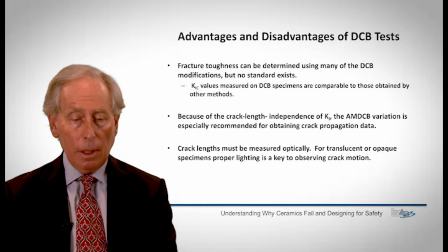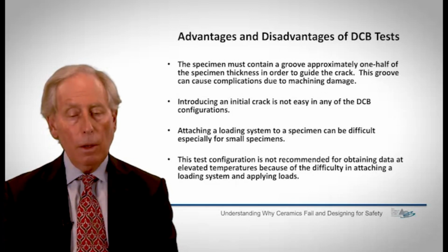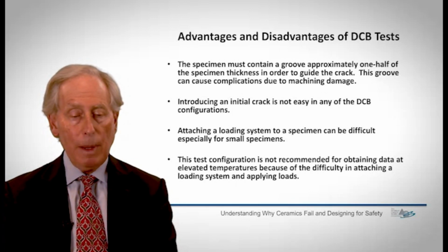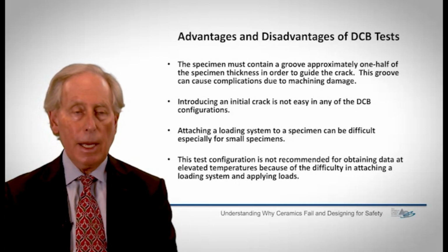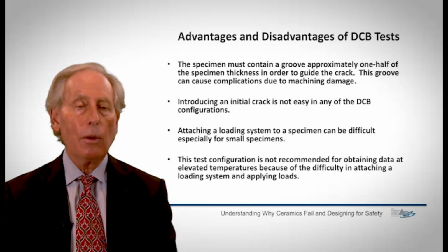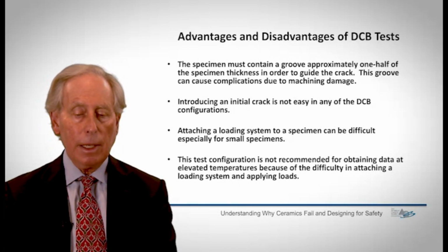In addition, I mentioned this groove. The groove is about halfway through the specimen in thickness to guide the crack, and the groove could cause complications due to machining damage in the material, etc. So this is a very useful test, for example, to look at slow crack growth behavior in materials. I would not say it's the best kind of test to get a critical fracture toughness value.